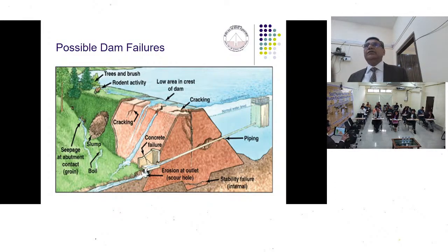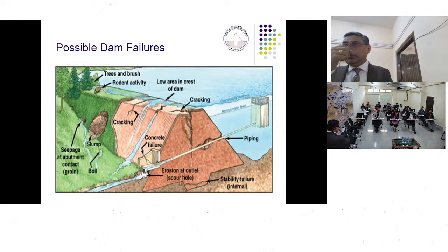So when you are going to visit your structures, if we are going to find any of these unusual things, then we need to be a little bit precautious and we need to monitor it first of all. It's not that as soon as you see a distress, you immediately start working on it, because the cause of the distress is not known.